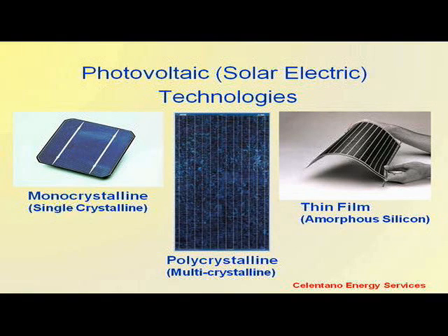This is where molten silicon is poured into an ingot. Crystals form in a random pattern. The crystals are then sliced into wafers. The wafers are made into solar cells. The cells are arranged on a panel, and then the panels are arranged in arrays. And then there's monocrystalline. This is the most efficient in terms of its energy production, although it also has the most expensive production technology.